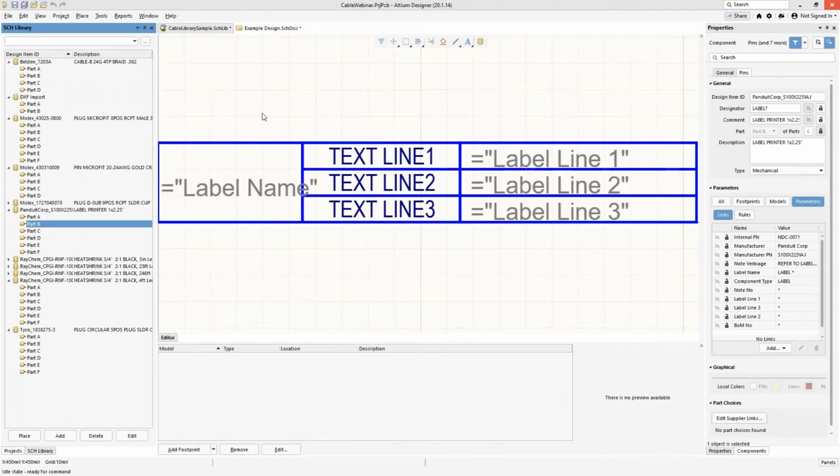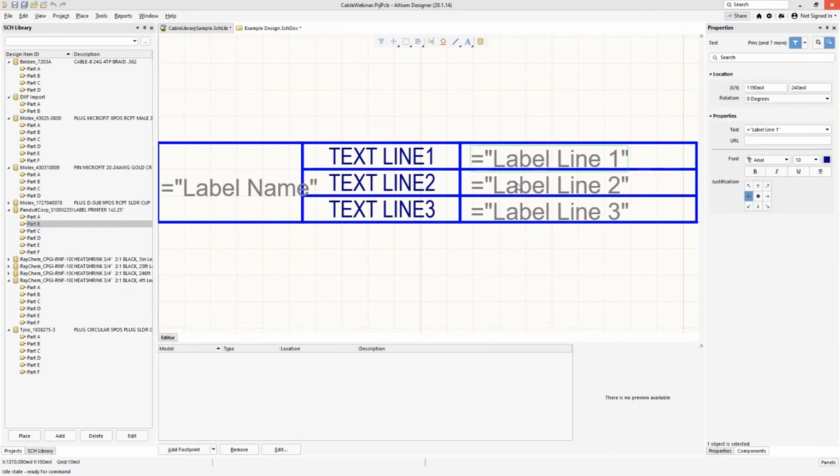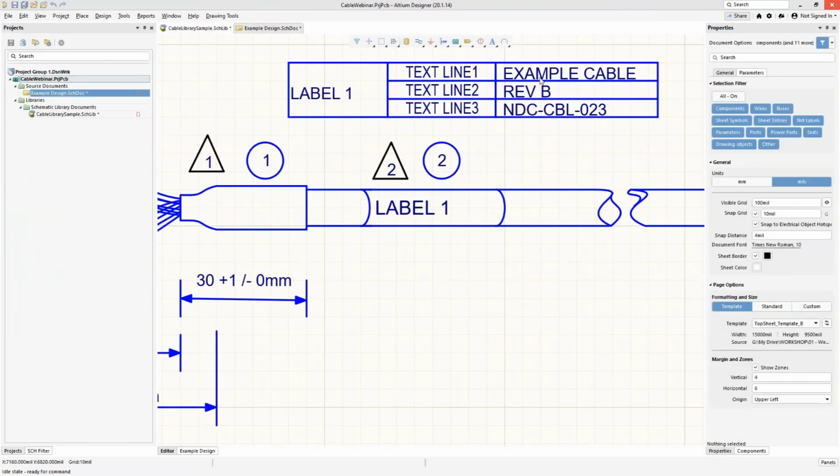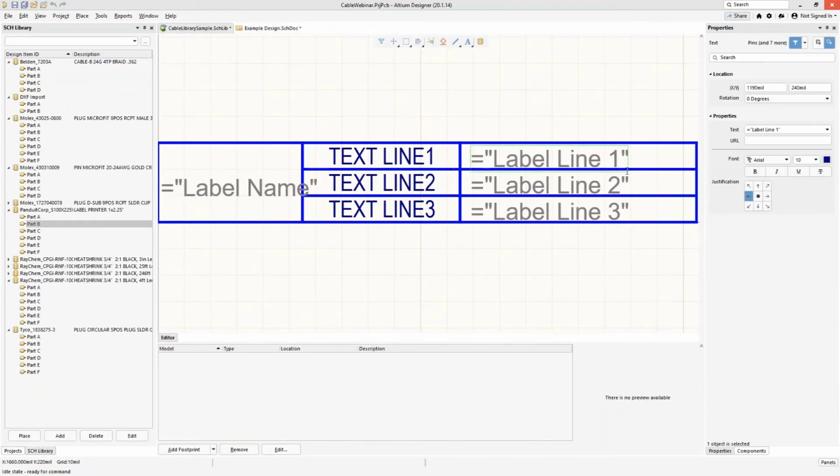Let's take a look at B. Here, we need to know what to print onto each label. And again, all of these used to be just straight up parameters. You turn on the parameters and stick them in, but now we're using the text to do this. By the way, there is a caveat with the text. You want to get it right because once you place this in, I can change this information here, but I really cannot get into its properties after this. So you want to make sure that you have this set properly in the library, like the color, the justification. The justification is really important. I'm glad they've added this in here. Your fonts, whatever is necessary to get this right, because once you put it in the schematic, all you can change is the actual text. You cannot change any of its other properties, at least as far as I can find.